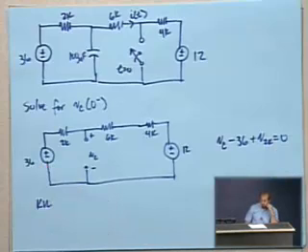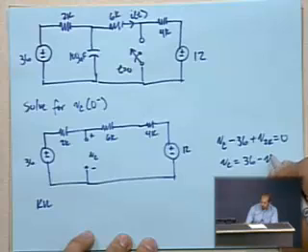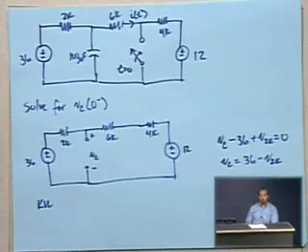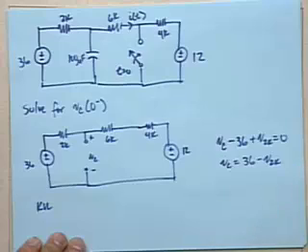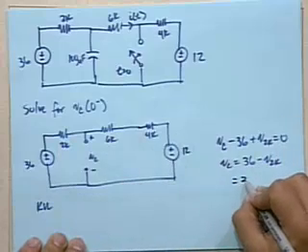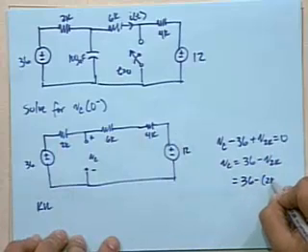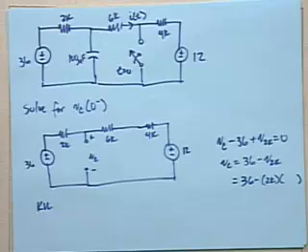So what that means is that the voltage across the capacitor is 36 minus whatever the voltage is across the 2K resistor, and that's just the KVL around here. But what we need to know is what is the voltage across the 2K resistor. To find that out, we need to know what the current is that's running around this loop, because that'll be 36 minus 2K times some current I. So we need to find out what that current actually is.